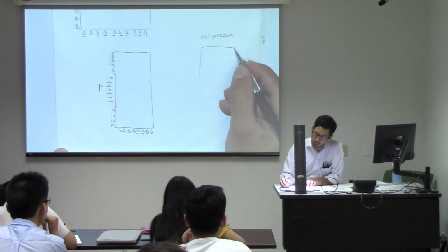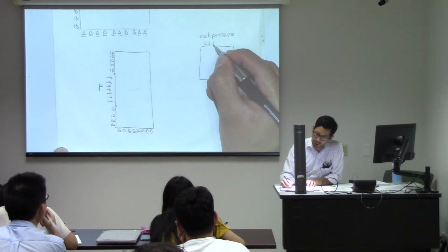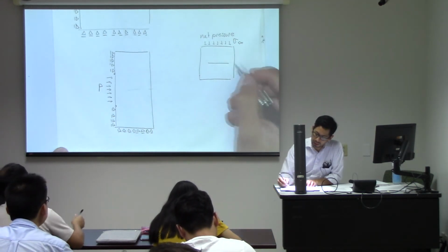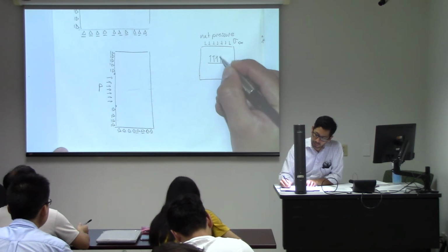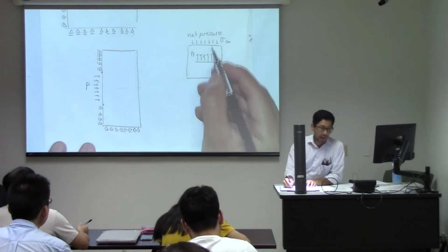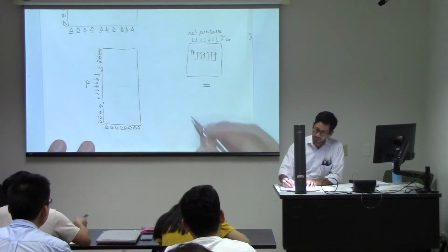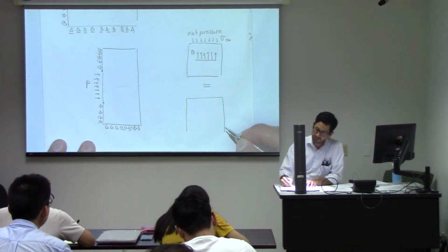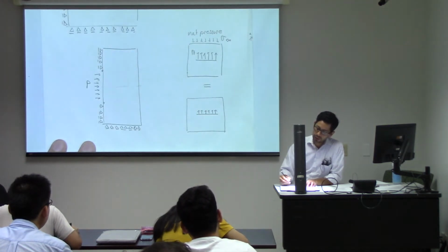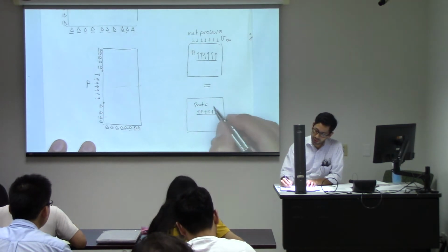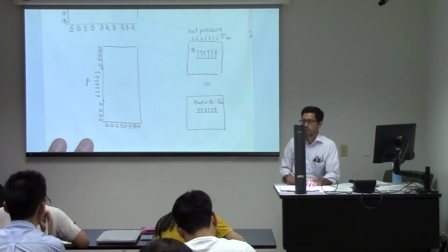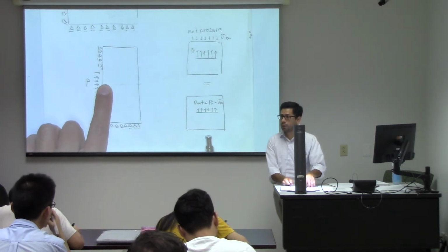similar to the wellbore, if we have a far field in which you have a stress coming in this direction, sigma infinity, and inside a fracture you have a pressure PF which is higher than the far field stress, analyzing this problem is the same as analyzing a problem with no far field stresses and just putting a value here, which is the net pressure, where the net pressure is going to be the pressure in the fracture minus the far field stress. And this is what I'm asking you to do in this problem.